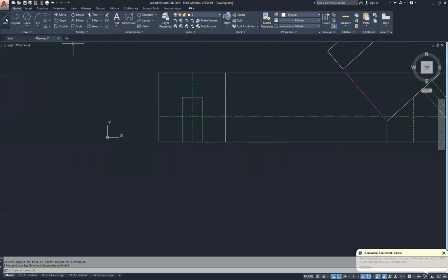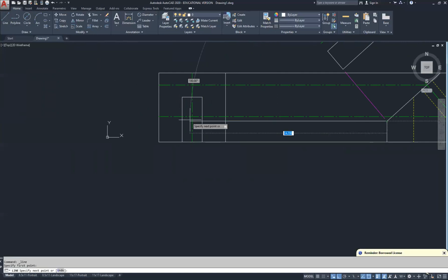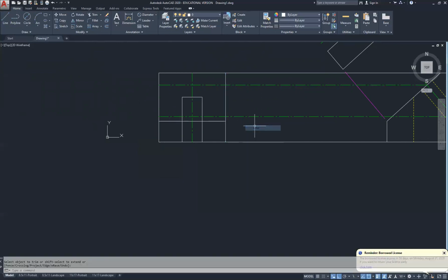One line that I missed to project, I need to project this line here, coming straight across. I click enter. I'm going to go ahead and use the trim command, using the right-hand side to cut this. Click enter. Right-click, repeat trim. I'm going to use these two lines as boundary edges to cut this.